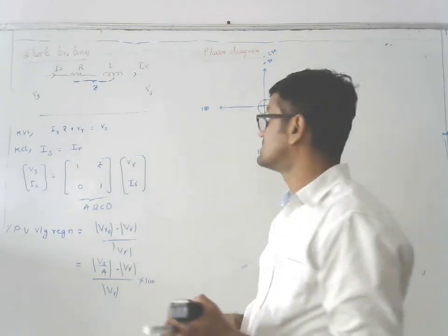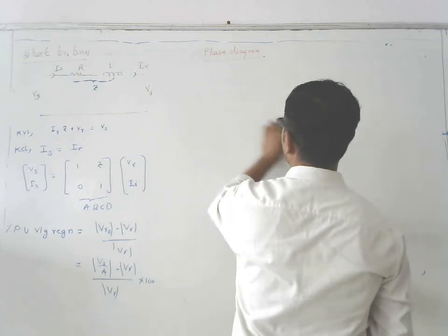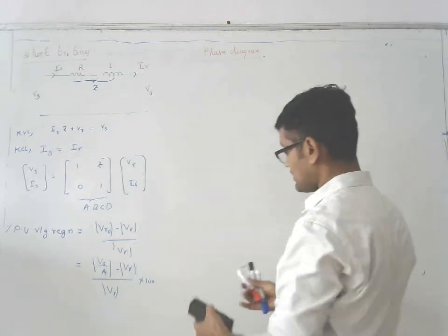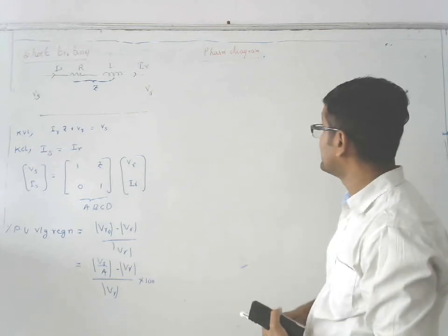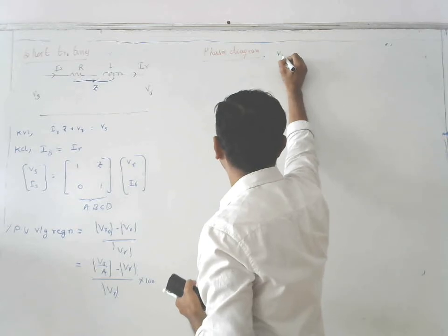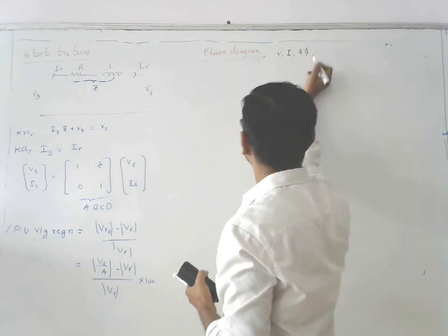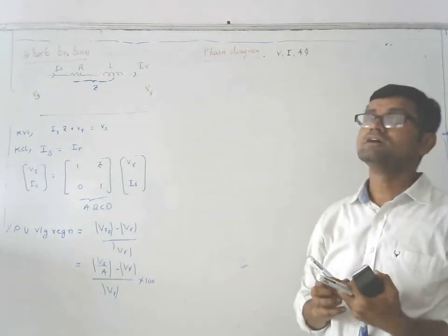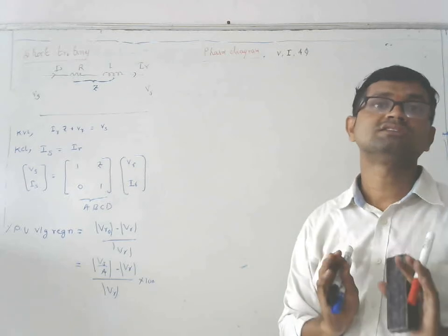Now, while drawing a vector diagram, not only for a transmission line but also for a transformer, generator or motor, in the phasor diagram we represent currents, voltages and fluxes only. Why? Because these have the same frequency. What we discussed is that vectors rotate anti-clockwise with constant speed. If they move at constant speed, only then can we define a vector diagram.